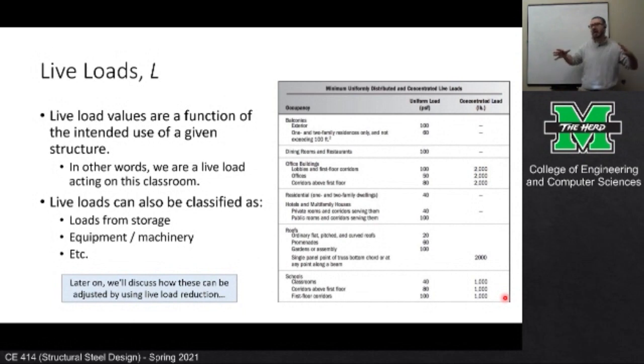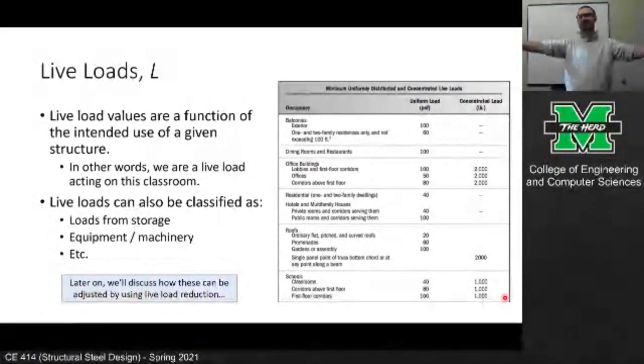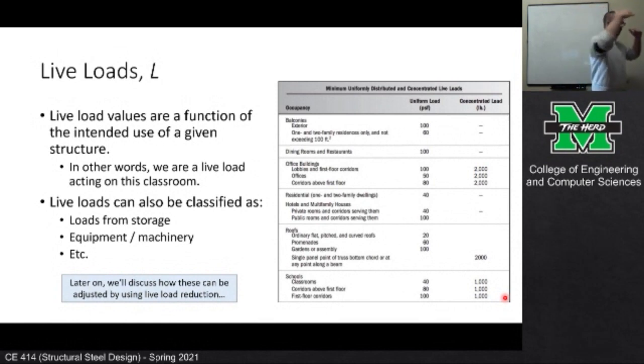Like the layout of the hotel is very set in stone. Here are the hallways, here are the rooms. When you're designing a commercial office building, for example, typically structural engineers will design the entire floor system as if it's one big hallway, because the developer wants to be able to sell or rent this space out at so many dollars per square foot.